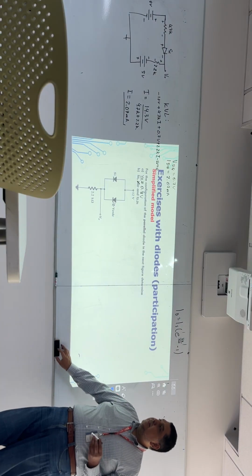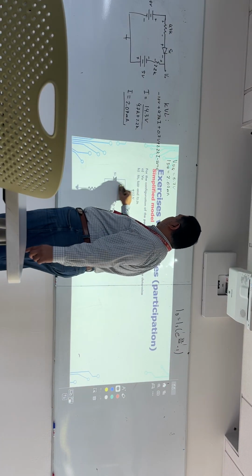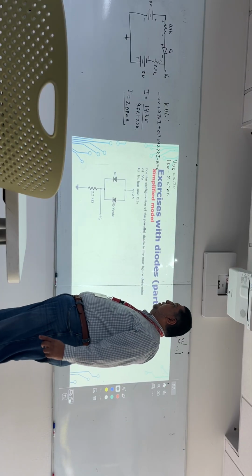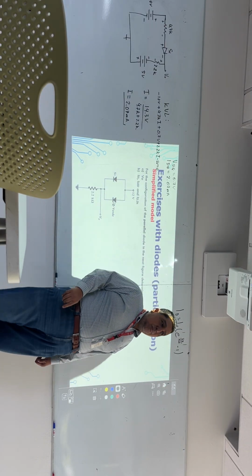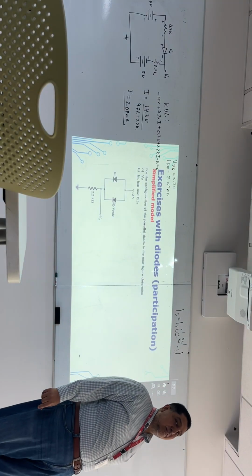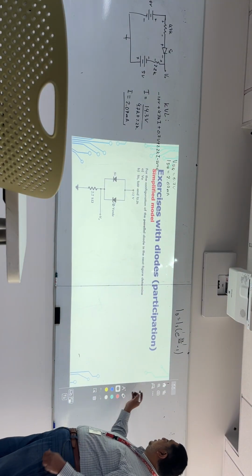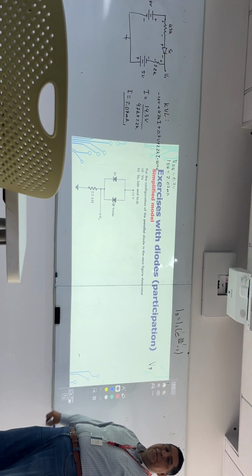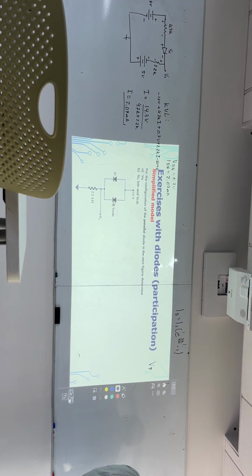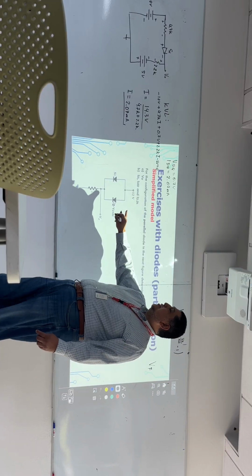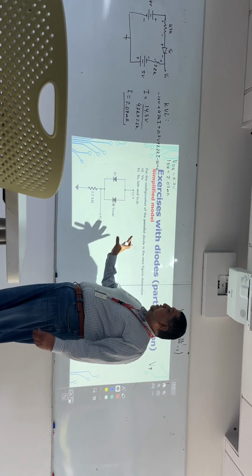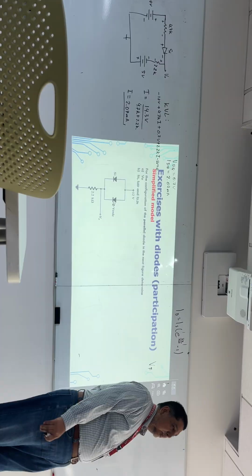So let's understand the basics. First of all, since these two diodes are connected in parallel and they have different activation voltages, when I say activation voltages, I am talking about VF. You remember this is the forward voltage. For silicon it is 0.7, for germanium it is 0.3. For an LED, we should consider what color is that diode. So in this case, this is 0.7 and this is 2 volts, because you cannot have the same voltage.